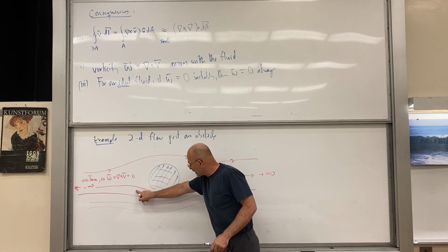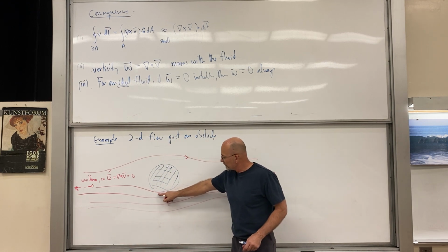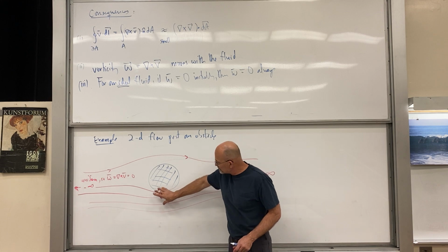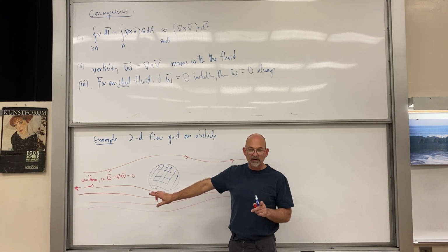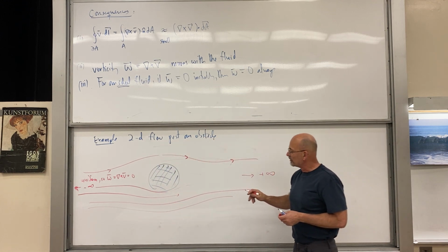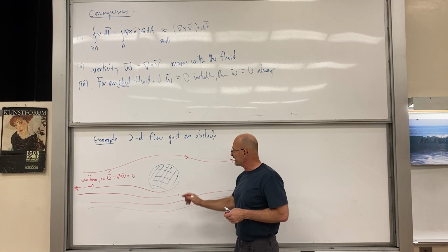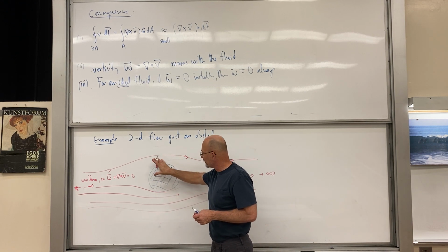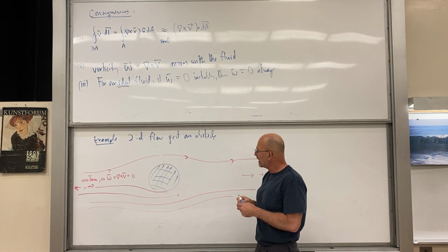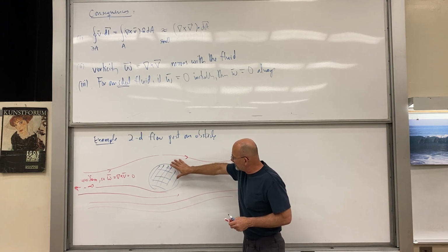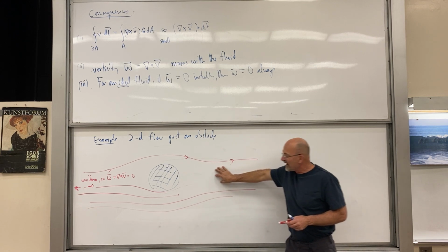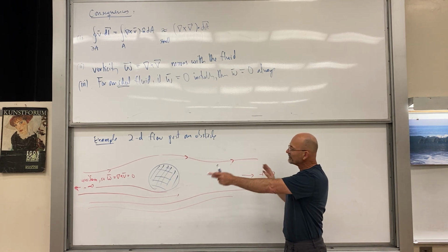some of these streamlines are going to go along the surface even. They're going to end up going along the surface, or they'll be very close, and then you will actually, not from Euler's equations. From Euler's equations, you can actually get a smooth flow all the way through here, no vorticity. But in reality, these surfaces, or the behavior around the surface, is not going to be that smooth, and it's not going to be vortex-free. The consequence of that is that instead of this smooth picture here, in reality, you're going to develop vortices and even turbulence downstream. So you don't have that symmetry.